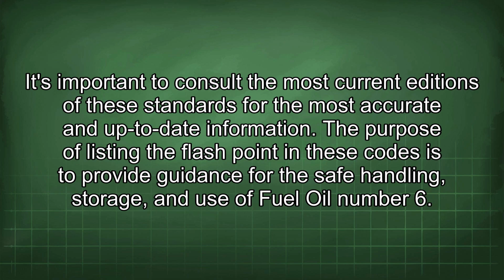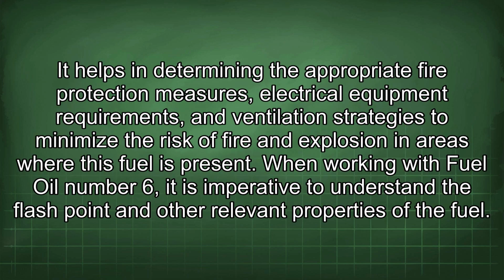The purpose of listing the flash point in these codes is to provide guidance for the safe handling, storage, and use of fuel oil number 6. It helps in determining the appropriate fire protection measures, electrical equipment requirements, and ventilation strategies to minimize the risk of fire and explosion in areas where this fuel is present.